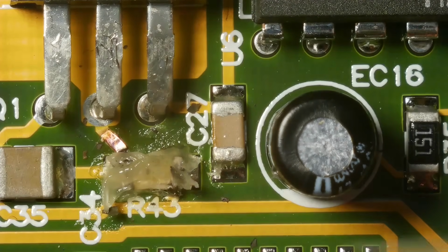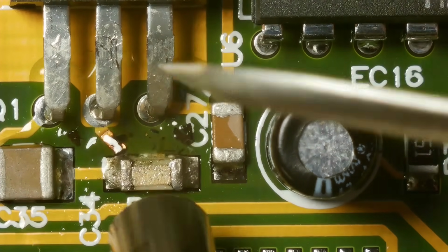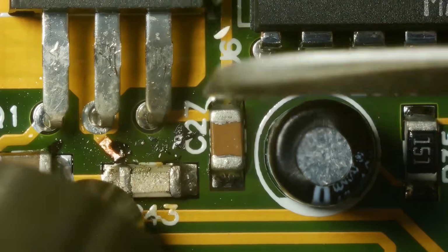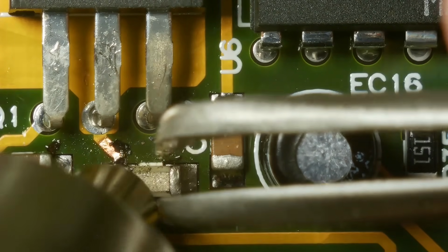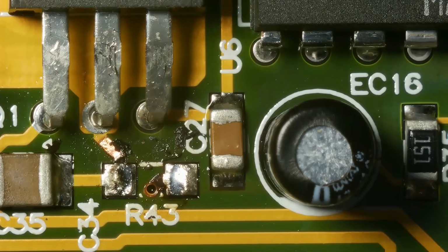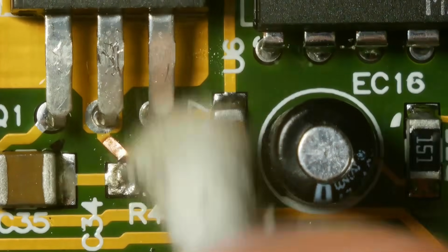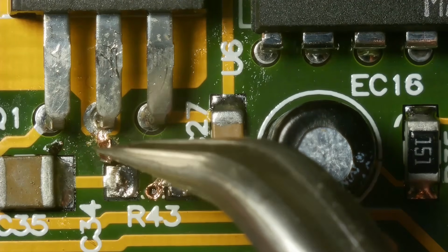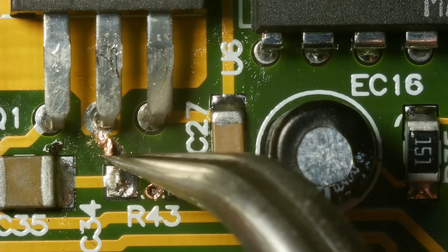Once again, the voltage regulator seems not to be shorted. I'm curious what actually has happened here. The regulator delivers 9 volts for the amplifier, but currently I'm a bit confused how a ground trace could burn like this. Let's remove the resistor and take a look underneath. So I removed the resistor, and as you see, the trace which goes to the regulator is gone. The PCB underneath looks a bit burned.